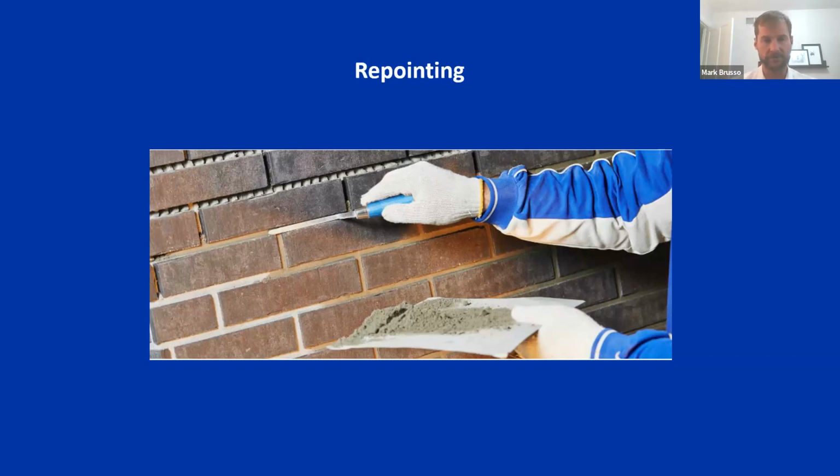Very, very important aspect of restoration work. It's really what it is all about, keeping that masonry joint intact and solid and free of cracks and filled solid, because that is one of our primary lines of defense in the fight against Mother Nature: the water membrane.